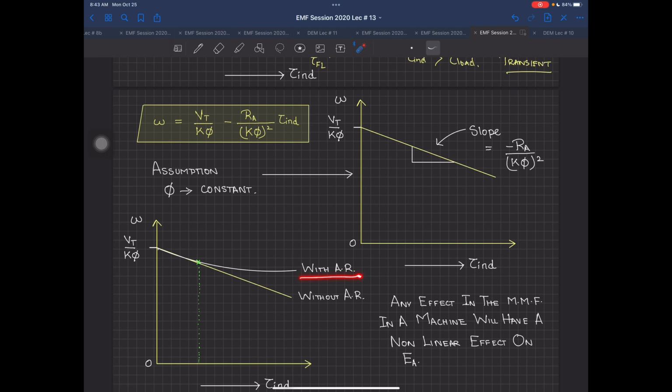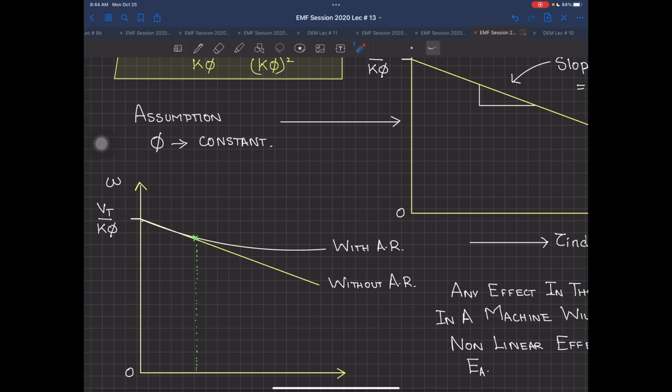a little dominant, which means when Ia is dominant, then this means that your flux phi A is going to be dominant over there. Then this phi A plus your phi F, and then you are going to get something phi R in your vector form over there. So what happens over there, as you can see closely, at this point, this green dotted line marked, at this point armature reaction kicks in. So what happens? Because of armature reaction, your flux decreases.